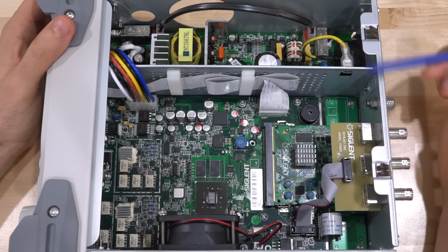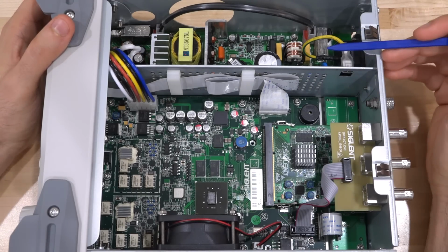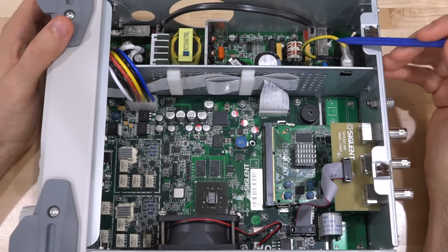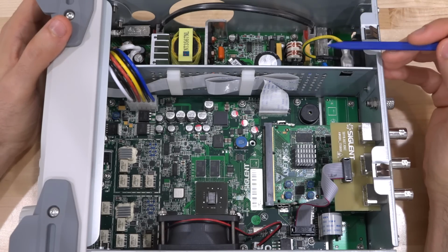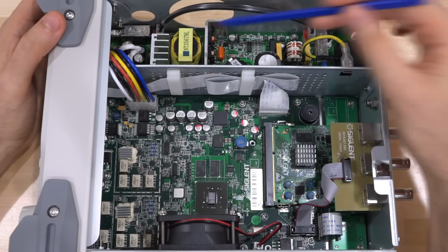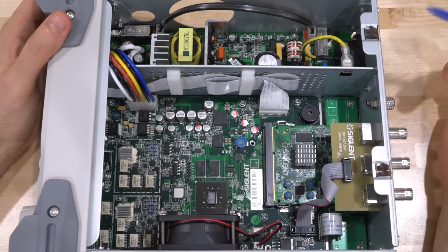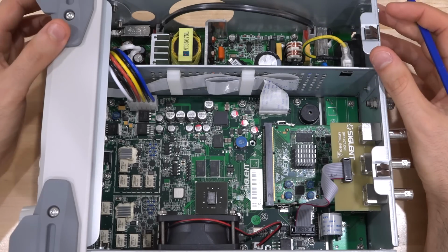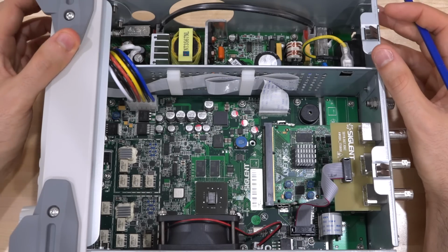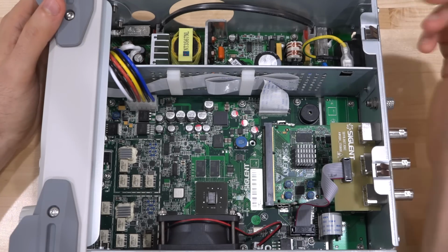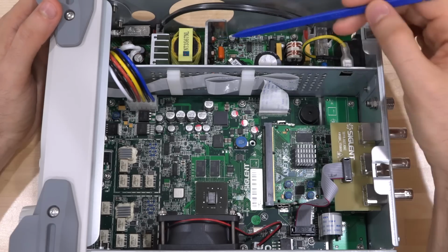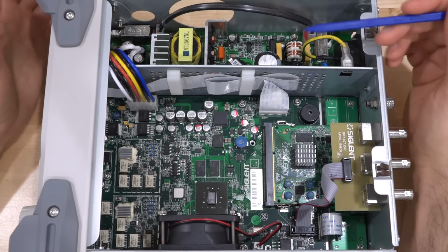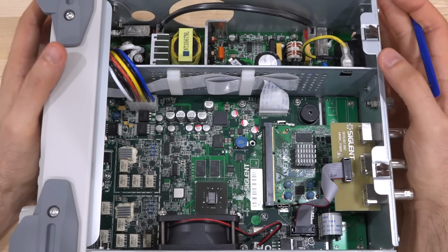Now, it has a very classic two-part design. At the top, we have our main power supply, which is reasonable. It has good grounding protection, input filtering, as well as fuse and everything. All the cables are nicely tied down. The component qualities are reasonable, nothing unusual there. We have a hard power switch, we can see at the top left corner there, as well as the fact that the thermal characteristic of this power supply is reasonably good. And this is because the overall unit's power consumption is not very high.